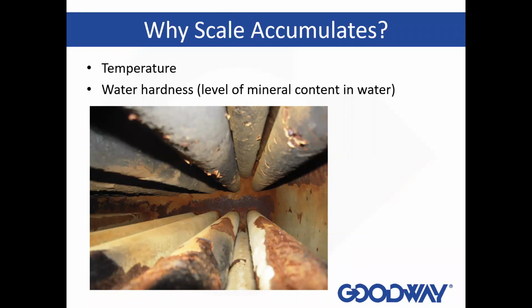The other thing that can happen is that the export steam, or the steam coming out of the boiler, goes from the vapor stage and recondenses back to pure water and is brought back to the water. Now, the more you can bring back, the better. But a lot of times the export steam going out doesn't come back. So you're coming in with straight makeup water, and you're concentrating those solids, and you're ending up with these very, very thick scale layers.